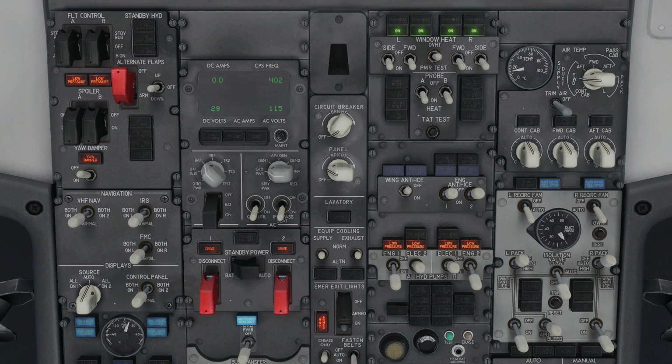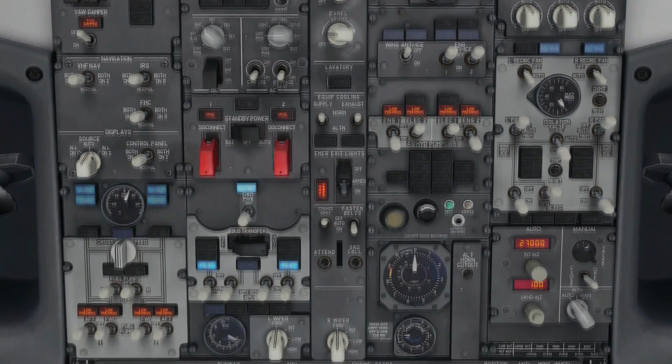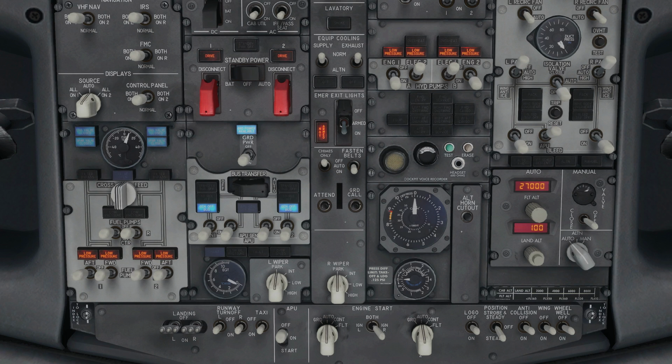Fuel before APU start is already loaded. Cruise and landing altitudes set, which they are. You'll change them to whichever you're going to do, but that has to be done. So I will change that once I go into the FMC. Next up we've got our passenger cargo and fasten seatbelts, so they'll go on to auto fasten seatbelts. Route, perf init and N1.